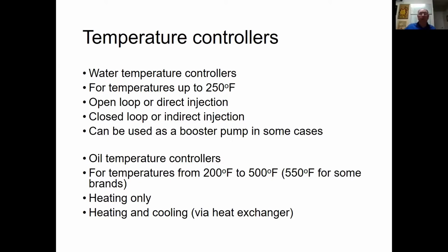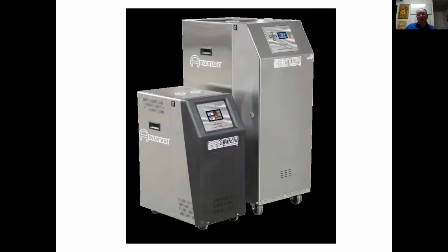Again, in water temperature controllers, especially open loop, it's not that critical because the cooling valve typically is large enough for just about every application. But in hot oil units, the heat exchanger really needs to be paid attention to. Again, here's a typical sample of standard temperature controllers. The small one typically is up to 16 kW, 3 horse. The larger one is 5 and 7.5 horse and 34 kW. Believe it or not, the hot oil units that we offer are in the bigger package.